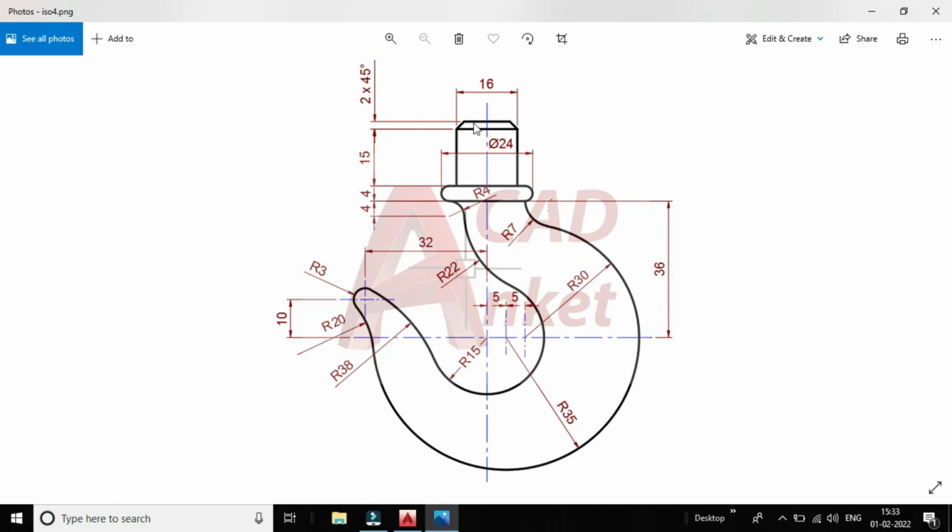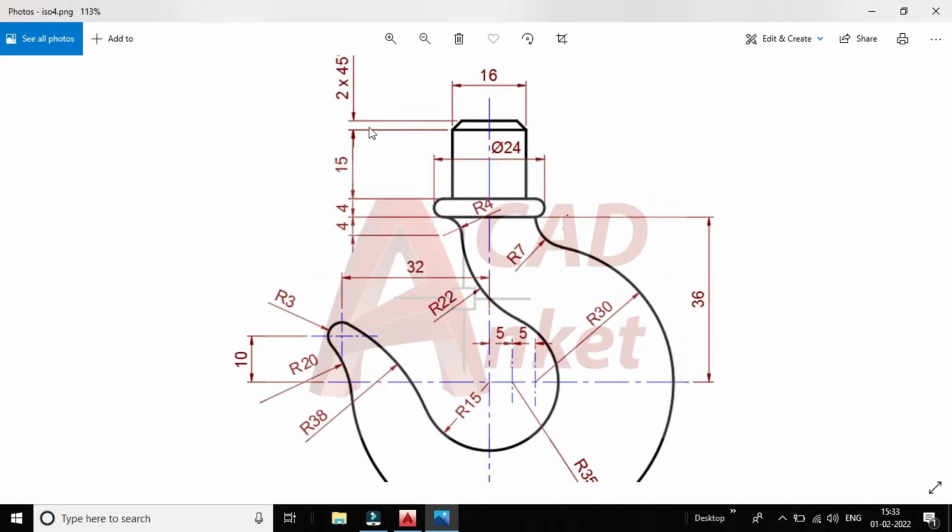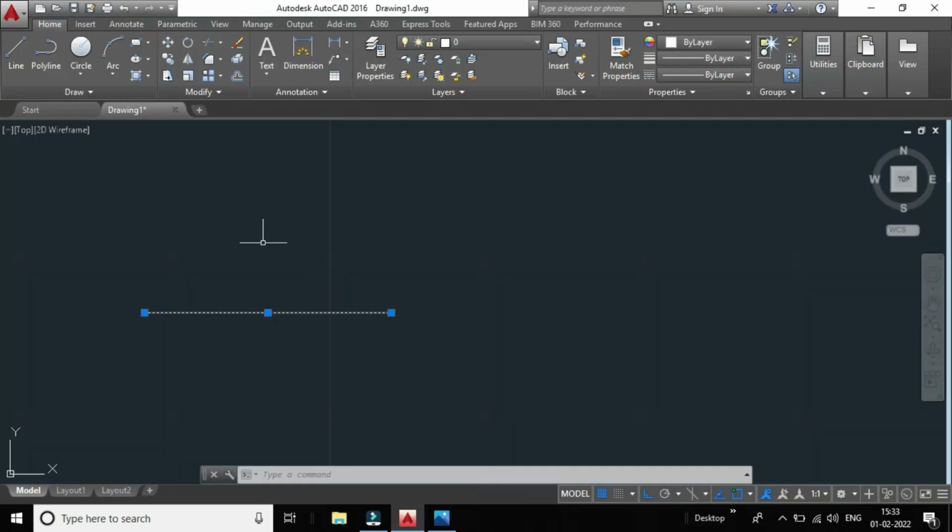For that, go on here and give it as 2 mm. Click on this offset option here. Specify the offset distance. Let the offset distance be 2. Click on enter here. Click on this option here. Here it has been given.